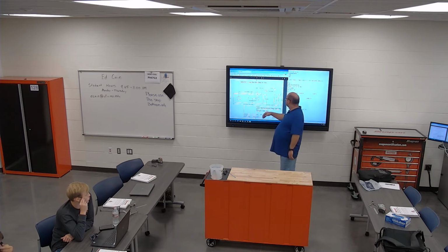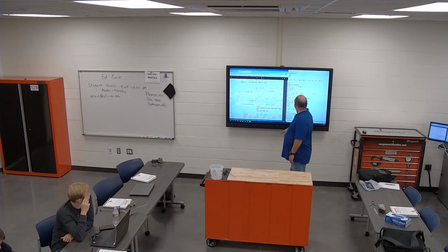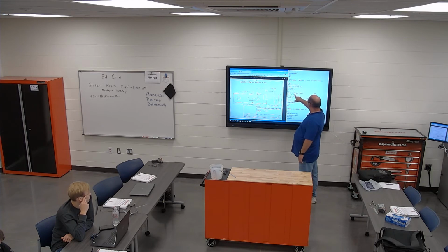Right, because it still thinks Z0 is here. So you would take 25 divided, and then you add it to the 875 to get how deep you want to go. Now add how much you took off. Oh, that's right, yeah. It's about 125. So it'd be 150-ish. So you should come up with this. And the feed rate, we'll go over how to do those in a minute. X, Z of negative 1.87.